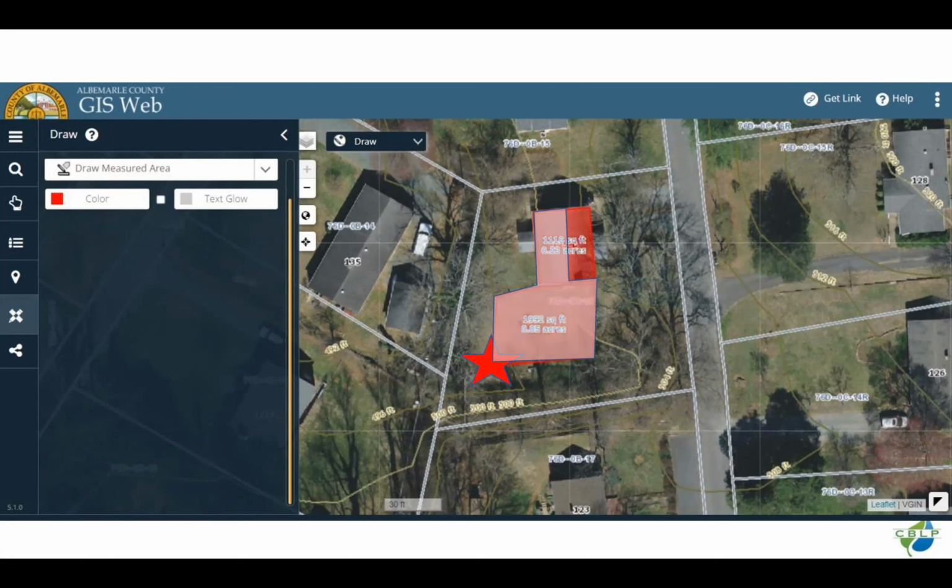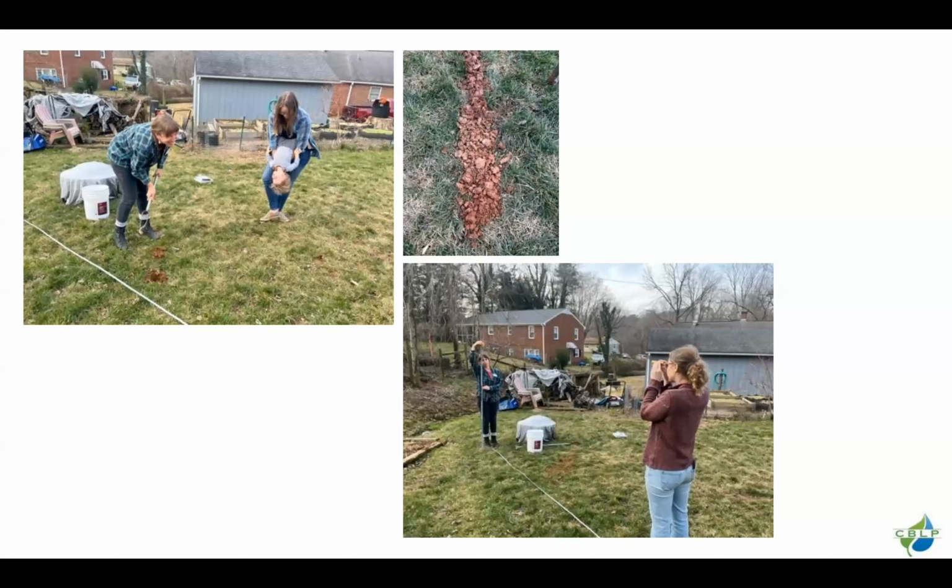If that's our BMP location, and we look at the downspouts and the drainage, it was this downspout at this corner, draining a gutter that ran along the house like this. So we know this half of the house would be in that drainage area. And just looking at the topo, this part of the yard also seemed to have a gentle slope down in this direction, not steep. So that's going to be the drainage area if a BMP was put in that location. So always be looking at site assessment. Think drainage area. The three most important things are the drainage area, and the drainage area.